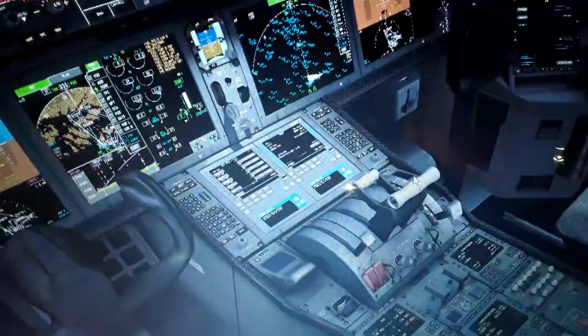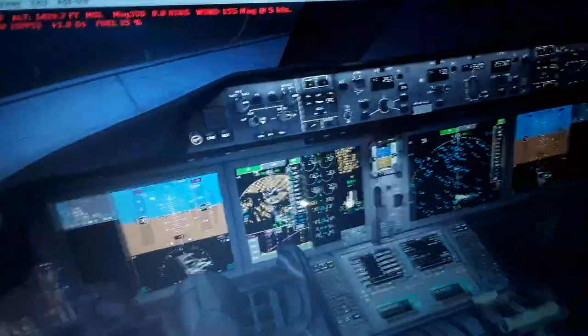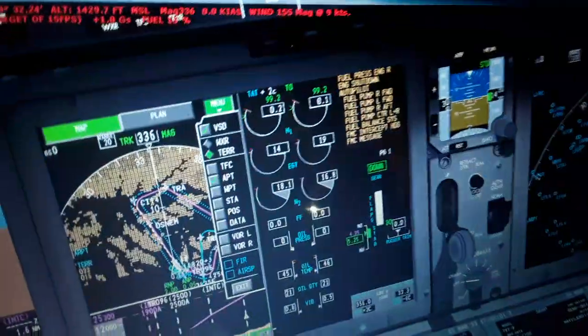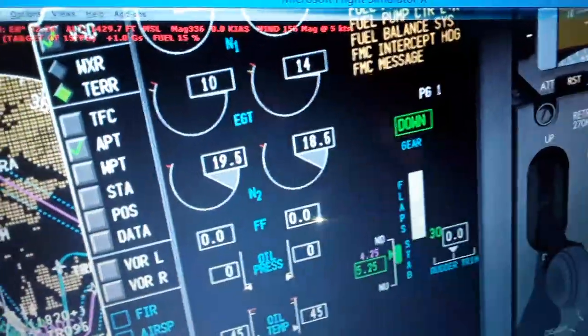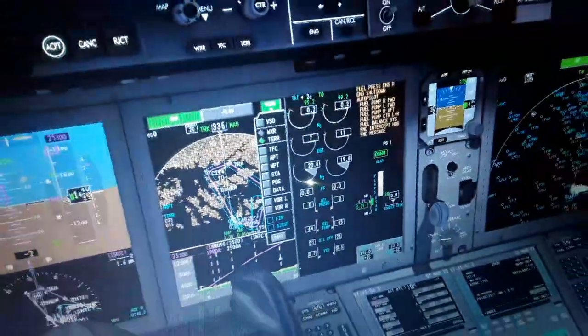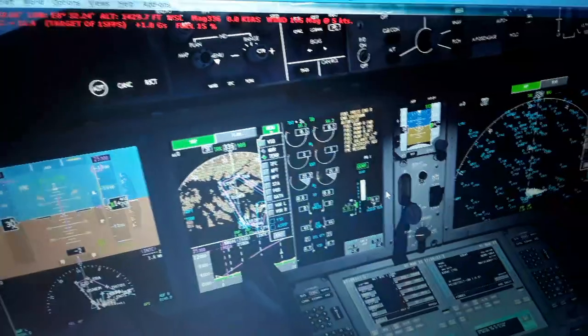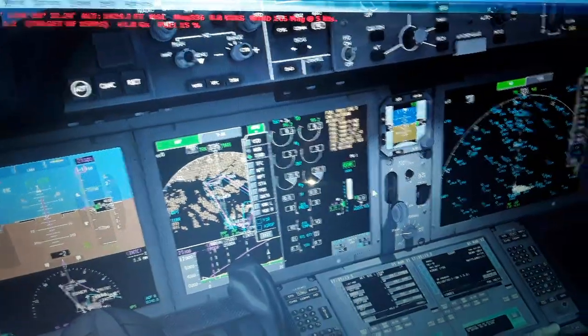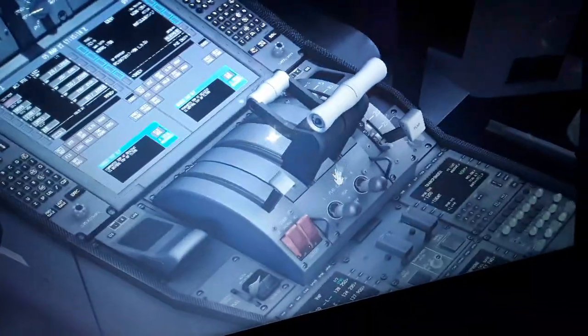We go in the overhead, auto start both engines, left and right over here, auto start to the on position. You see the yellow reconfiguration. We have pressurized air right now from the APU to supply pressure for the engine start above 20%. We're gonna be having the fuel flow for the engine. So you can see we still have pressurized air over here, so we can start the fuel flow right now very quickly like this. Fuel control, left and right on.